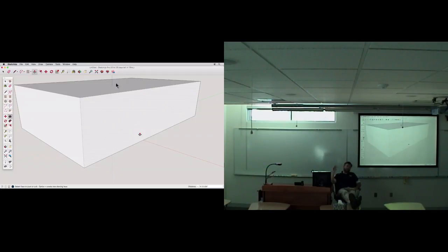So if you try to build this box from 6 different rectangles and then turn them around and connect them together to build the box, it creates all kinds of problems if you don't connect all the edges and corners together exactly. And if you don't connect them together exactly, then SketchUp will not create this solid object. However, if you push and pull the sides, then SketchUp automatically creates a solid box.